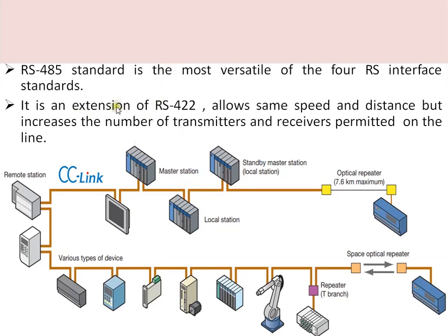Here we can see that many devices are connected on the same bus. PLCs, drives and remote IOs are connected on the same bus, and all these devices have the RS-485 serial communication feature. Along with this, for addressing these devices, which device needs to take the data and which device needs to take the control action, some protocol needs to be specified.